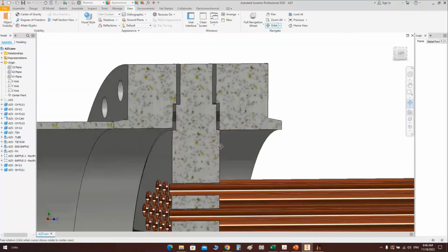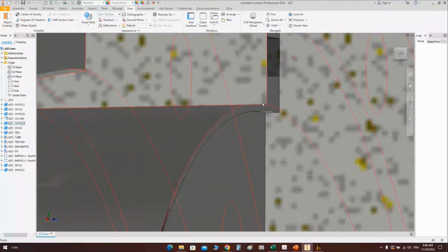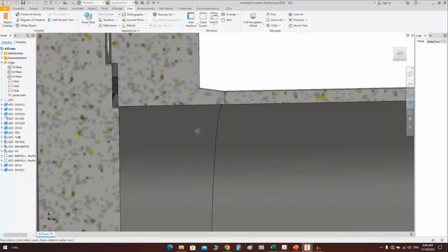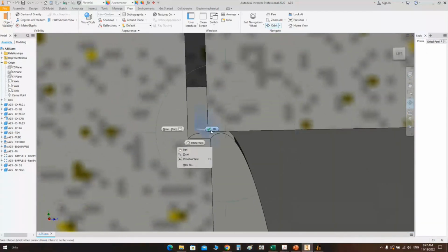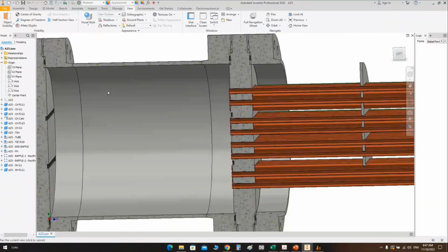So things like that, we can modify in one time after adding a clad on this side, because after adding a clad here, we need to decrease the raised face diameter here, and the same on that side. After adding a clad here, we will need to decrease the raised face diameter on that side.